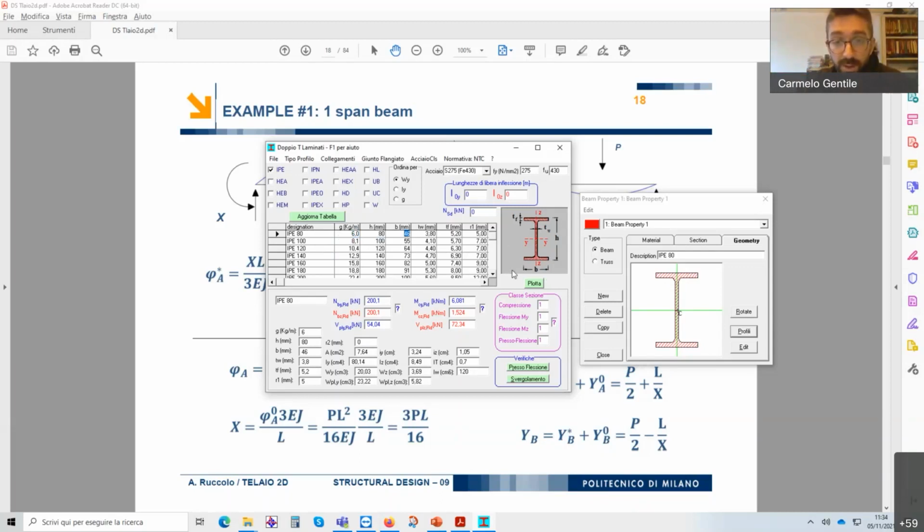The B, so the length of the flanges, everything is explained in this small drawing. TW is the thickness of the web here. TF is the thickness of the flange. And R1, R2, the area, and so on. R1 and R2 are just the curves of connection, the radius of curvature of these two parts, but they are basically negligible.